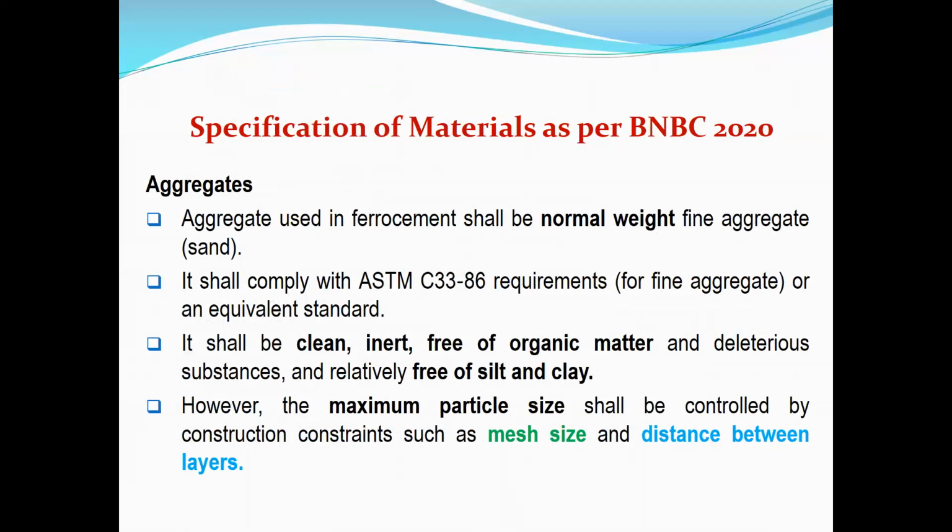Now, regarding aggregates. The aggregates used for ferrocement are normal weight fine aggregates, normally sand. And the specification of sand shall comply with ASTM C33 requirements for fine aggregates or an equivalent standard. Sand should be clean and inert. Inert means the material does not take part in any chemical reaction. It should be free of organic matter, free of deleterious, harmful substances, and free of silt and clay, because silt and clay will not serve the purpose of the sand.